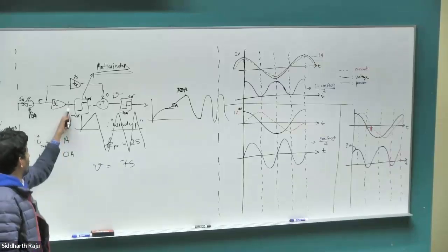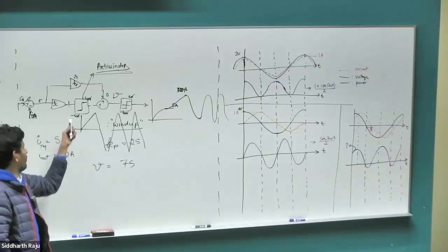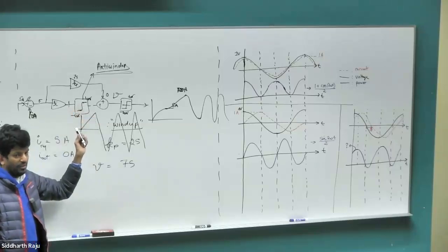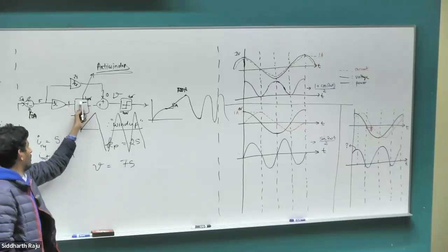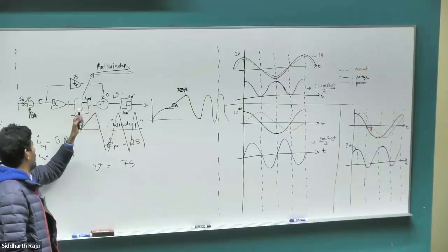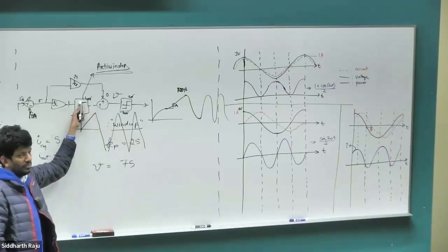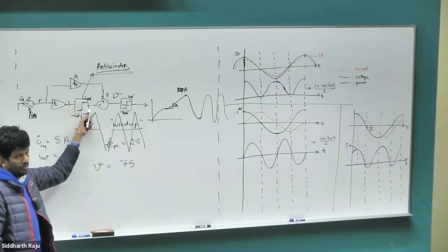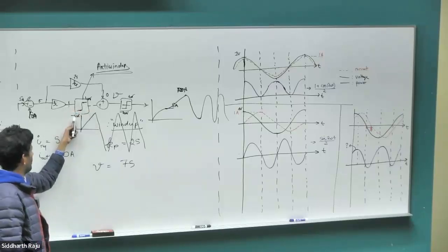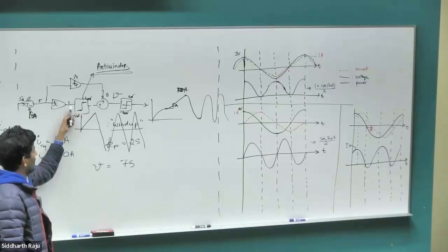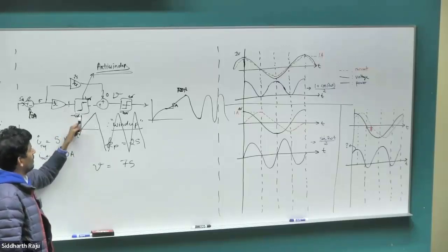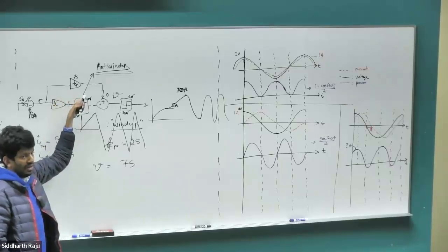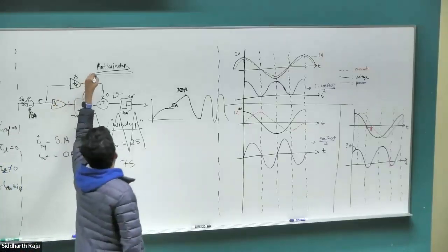All right? Until the error becomes negative. So if it has an error which can pull it down from 40, then it will go ahead and integrate. Until then, it will stop integrating. So if the integrator has reached 40 volts output and the error is positive, it won't integrate any further. If the error becomes negative, then it will bring it down, so it will start to integrate. Same thing again, if it reaches negative 40 volts and the error is negative, it will pull the output further down, so it won't integrate at all, it will just stop integrating. Once the error goes positive, it will start integrating back up again. So that's called the anti-windup, right?